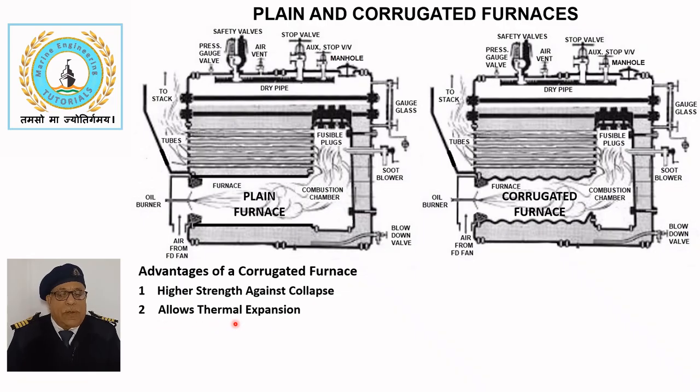Allows thermal expansion. Corrugations flex slightly to accommodate expansion and contraction of the furnace, thereby minimizing thermal stresses and the risk of cracking.